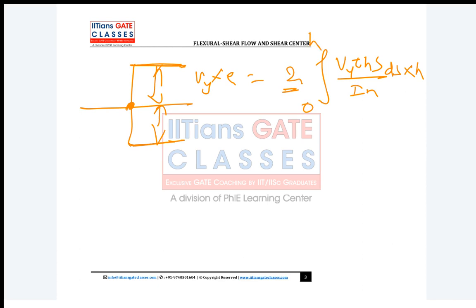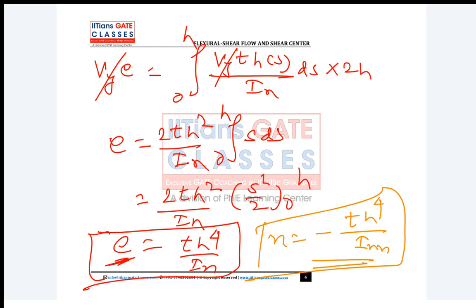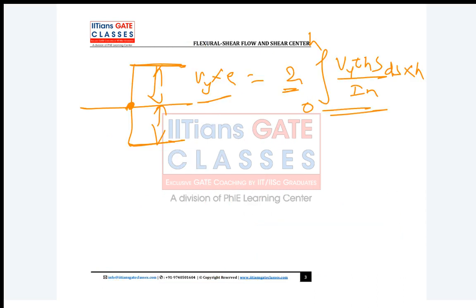So if you do this or if you do this, your answer is the same. Okay, is my point clear, guys? You can do moment equivalence about this point. What we did was take 1 to 2, then use the symmetry condition, and we can find the shear center position using moment equivalence.